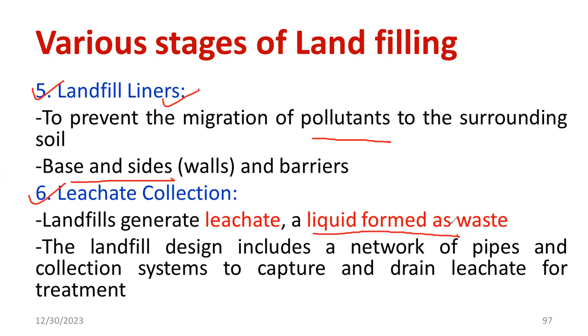Otherwise, it creates so many pollutants. It creates vector breeding insects, bacteria, etc. So landfill design includes a network of pipes and a collection system to capture and drain the leachate for treatment. That is very important. Just like a drainage, that liquid originating from the waste has to be removed at least once in 15 days. That is compulsory. Otherwise, that area becomes polluted and creates many health disorders. So leachate has to be removed systematically by using a large number of pipes or ducts.